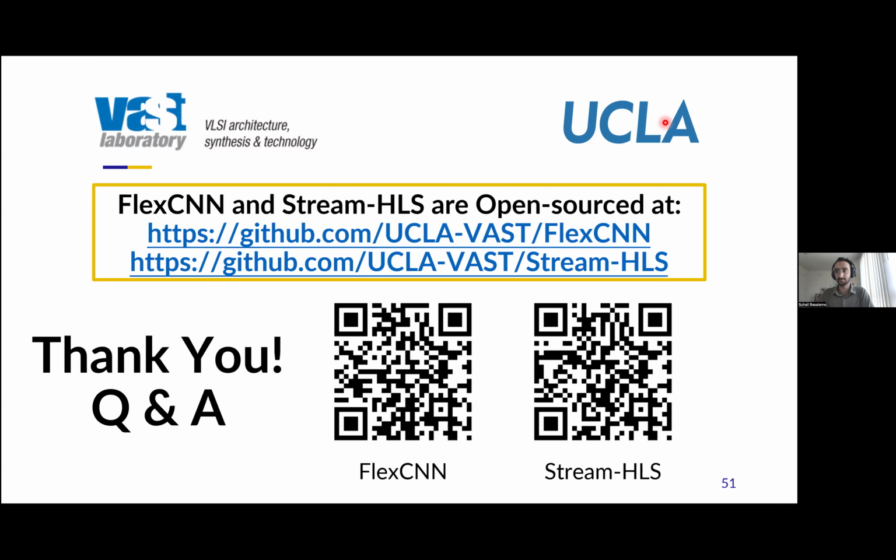So I have two questions. Go ahead. So for your Stream-HLS, you are doing this conversion from shared buffer to FIFOs, you need to perform loop permutation for the second kernels, right? So my question is that sometimes after you perform the permutation, probably you are not able to achieve II equal to 1. So how do you handle this conflict?